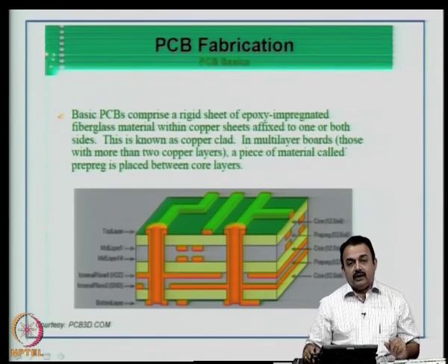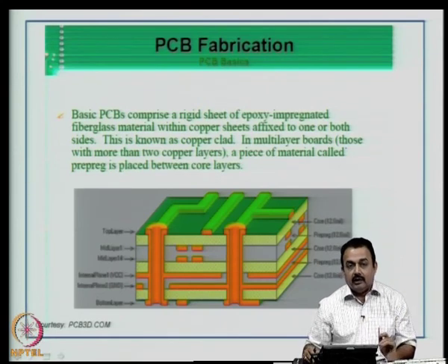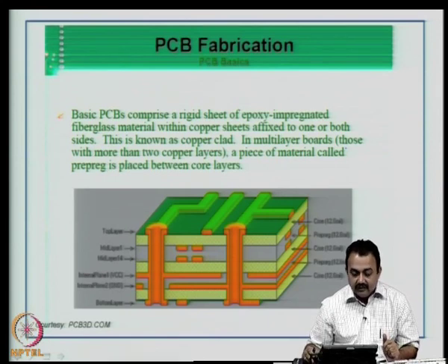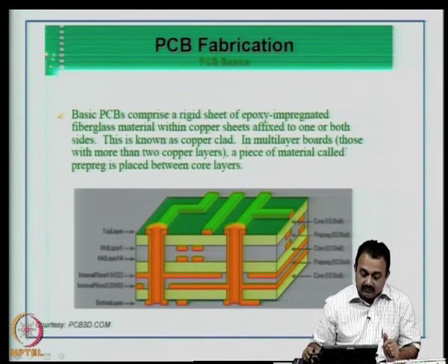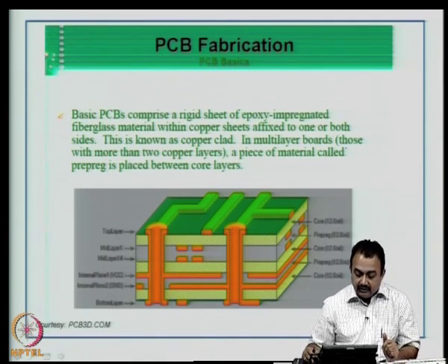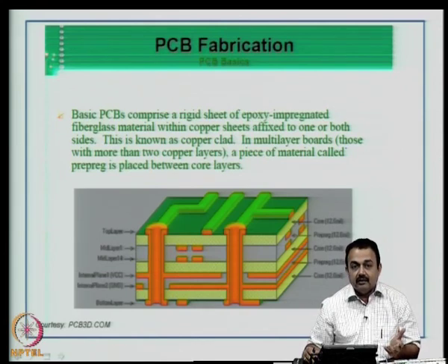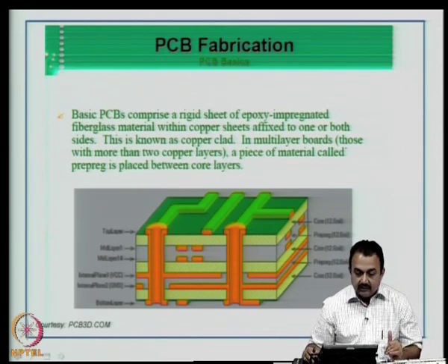So, that completes the Gerber file requirement that you will be able to create once you finish your CAD work, and now the board goes for PCB fabrication. So, as we have seen earlier, PCBs or printed circuit boards or printed wiring boards comprise a rigid sheet of epoxy impregnated fiberglass material with copper sheets affixed to one or both sides. So, you can have a single sided copper, double sided copper, and therefore, it is known as a